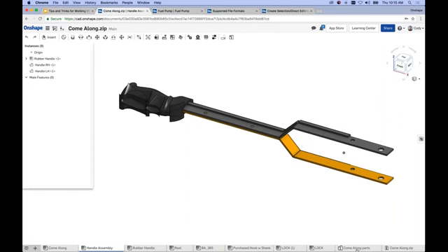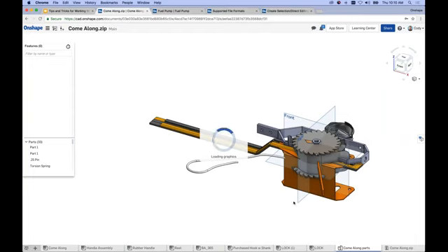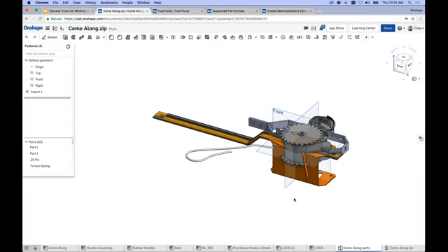One of the first things I would stress is when you import geometry, it comes in the orientation it was originally modeled. So in the Part Studio, all of the parts are brought together in their original orientation. In this case, these were modeled in a bottom-up manner, right? They're modeled independent of one another. But if you had brought in an assembly that was built top-down, what you would see is they would all be built with those contextual relationships in place.